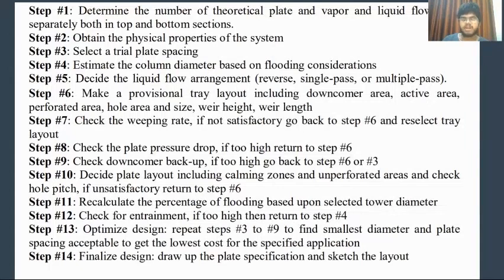Now, what is a weir? The depth of liquid on the tray is maintained by installing a vertical flat plate, which is known as the weir. Higher weir height gives more efficiency. The weir length will determine the downcomer area.